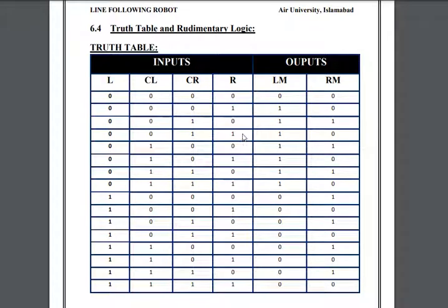If you can see this combination right here, 0 0 0 0, all these sensors are on white and they are reflecting the infrared light back at the sensor.